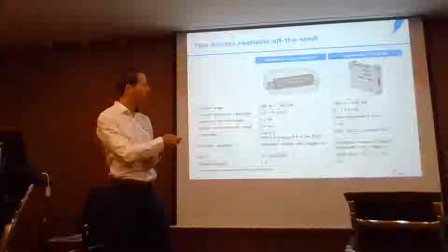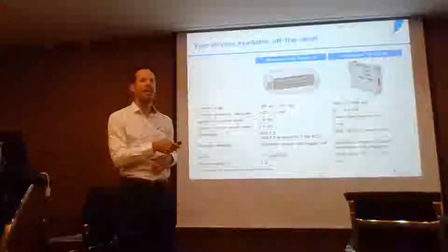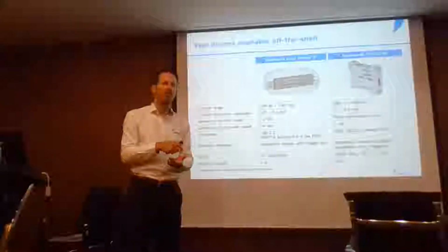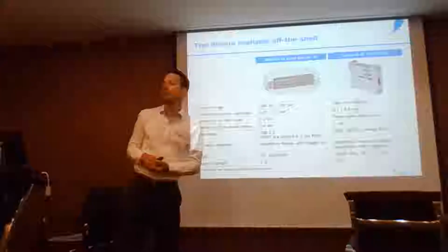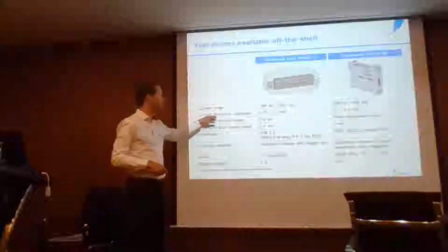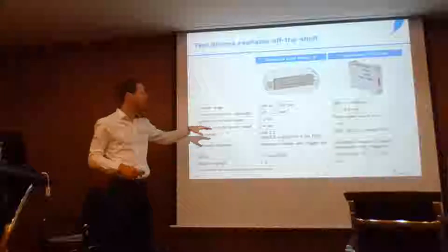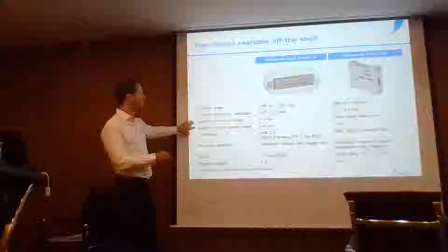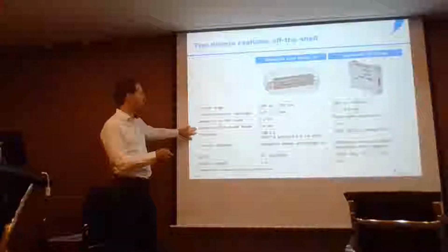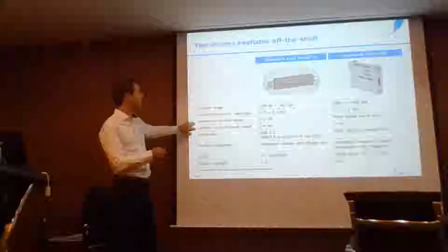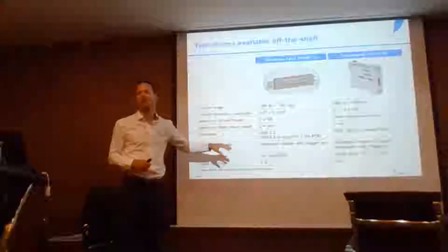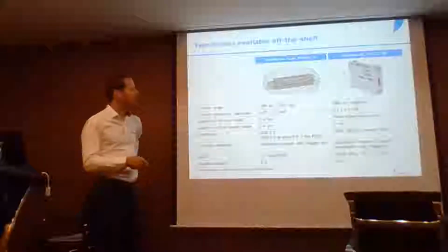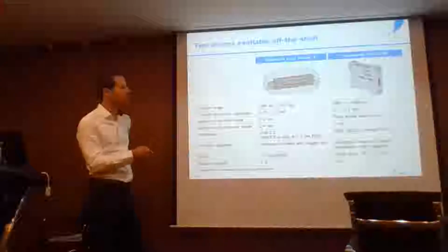Our driver cannot output any more, but the Gardasoft driver can do that. So if a 5D lens is not enough, then maybe with more power on the driver, you can get a bit more range. In terms of resolution and accuracy, they're pretty much the same. The latency is relevant here, in the focal power mode. It's very fast. In the case of our driver, there's a few milliseconds delay, because again, our microcontroller is not that fast. So it's a little bit faster to work with this driver here.